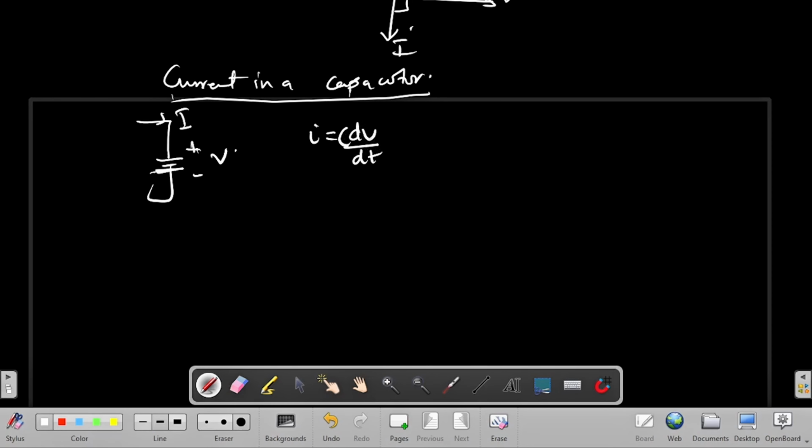This is the general formula. And as you know, the voltage in any AC is given as Vm sine omega t, is that not it? Therefore, to find my change in voltage over time, I'll have my C outside as a constant, my omega will come, is that not it? Then Vm cos omega t.